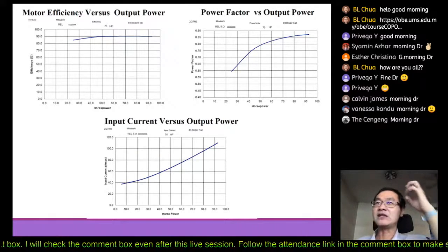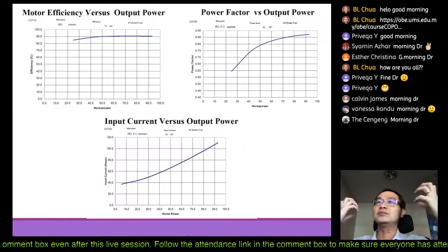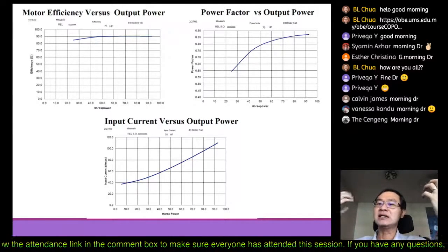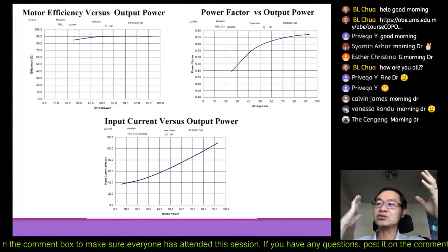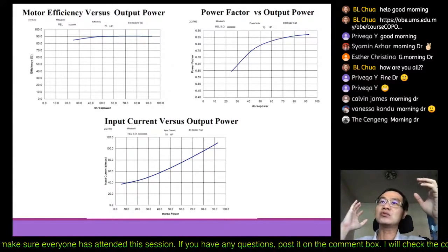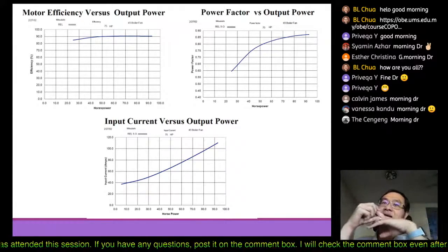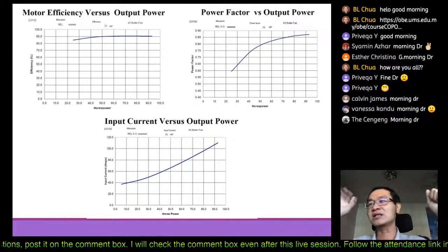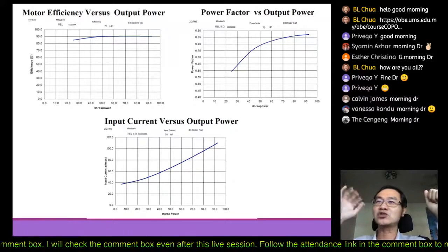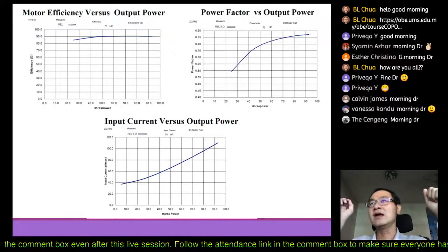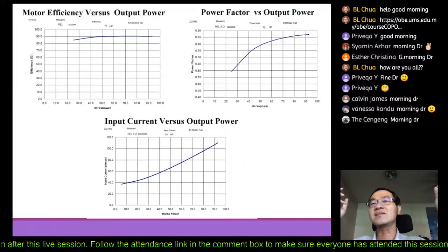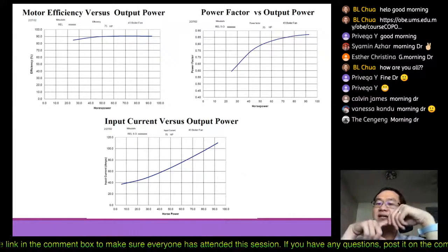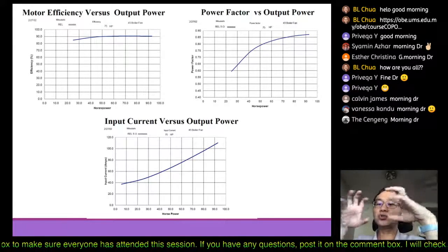Because of the increase of the load itself, due to, let's say, a lot of dust. So the fan is heavier to rotate, so the load is heavier. Also, when the blade is not balanced, there is a centrifugal force that creates a kind of fluctuation, then the load also increases. And there is also a possibility that the belt is stuck in between the pulley, so it requires more load to operate.